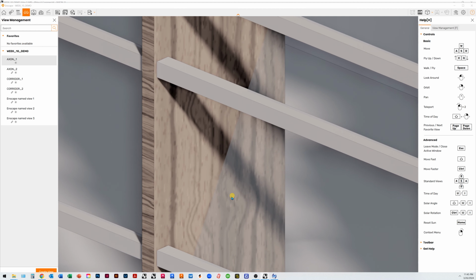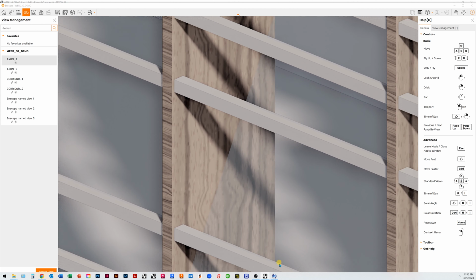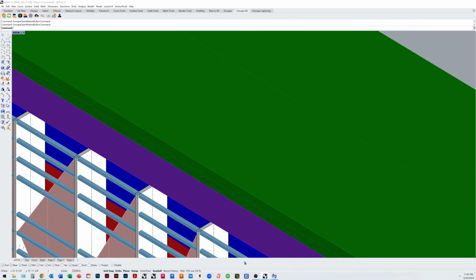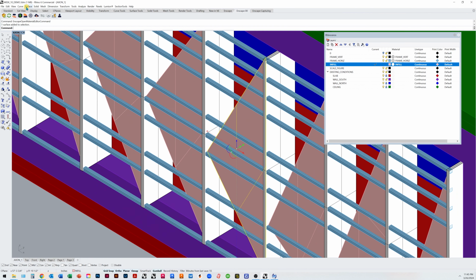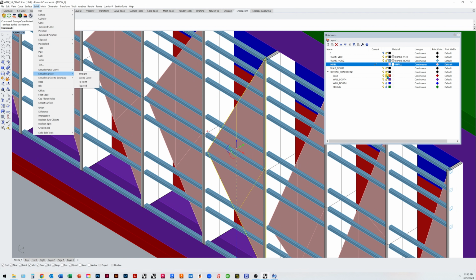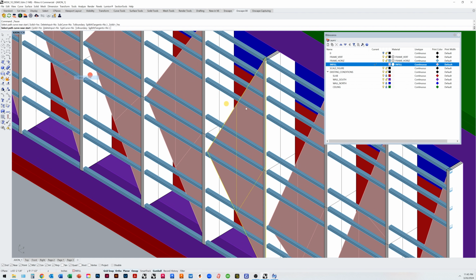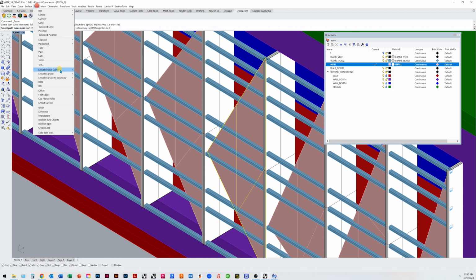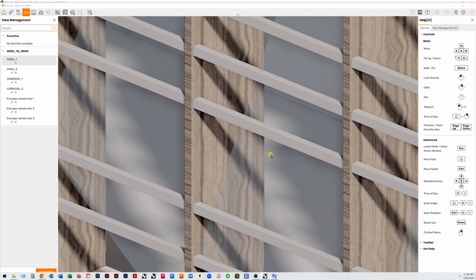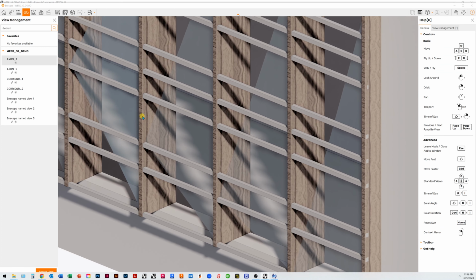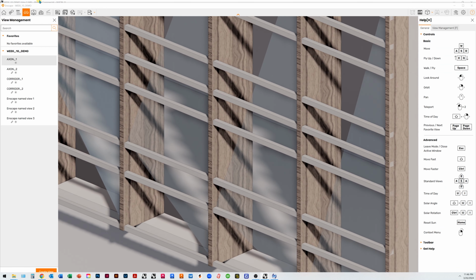So now these are showing without really any thickness because I built them as surfaces. But if I came back into my Rhino and I started to give any of these thickness, so if I took that solid and I extruded that surface, just like a quarter of an inch, then when I go back here, it's going to start to read with a little bit more thickness.